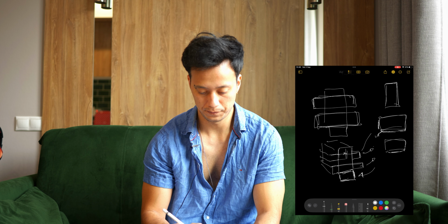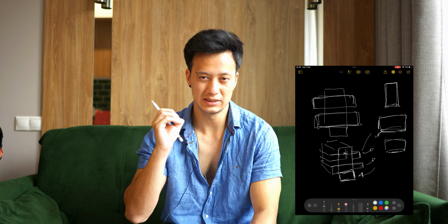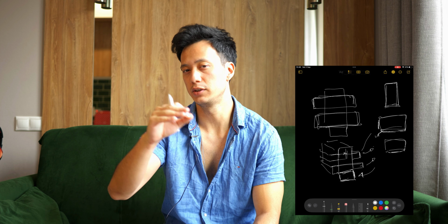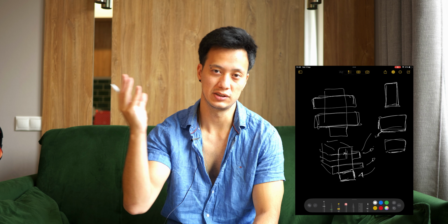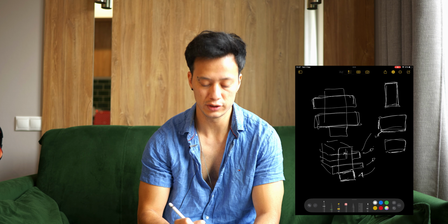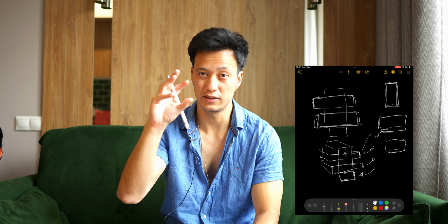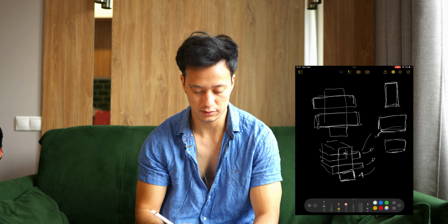So why are we doing this? Because whenever we start cutting with the knife tool, which is important to maintain the texture when we are using BoxCutter, so I'm just bringing a bit of spoiler of the video, but knife tool is what you want using BoxCutter for the Ian Hubert technique. We are not going to be using that for the blocking part, but then for the cuttings, for creating the holes, for the details, that's what we're going to use.